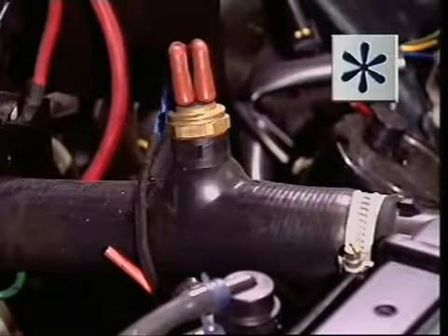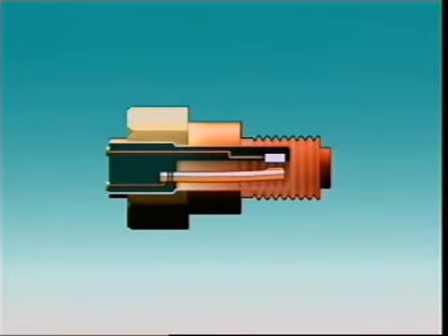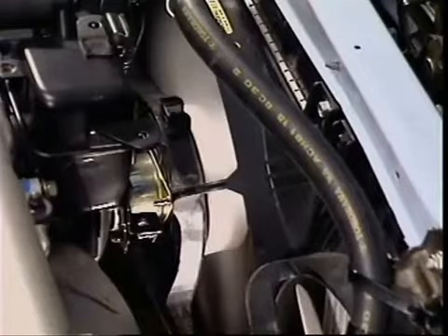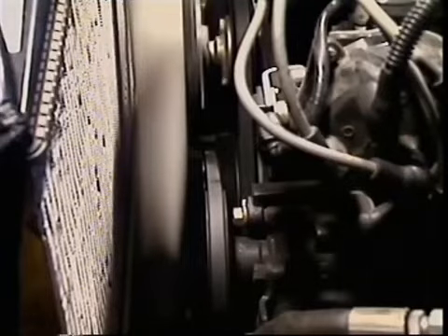A heat-sensitive switch in contact with the coolant can work like a thermostat and turn the fan on and off according to coolant temperature. Another way to alter the speed of the fan is with a viscous hub. This type of fan slips when it is cold, but as the engine heats up, it grips more and more.